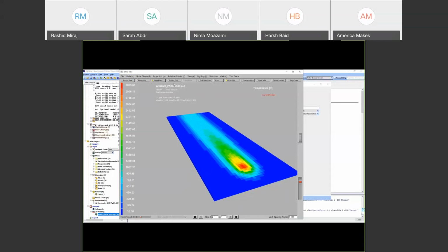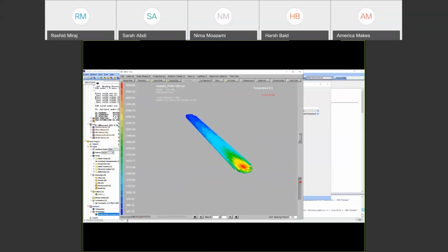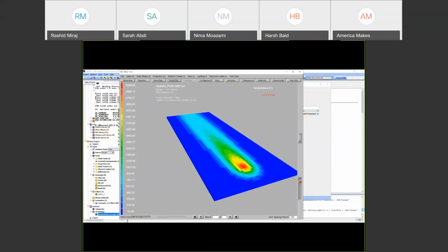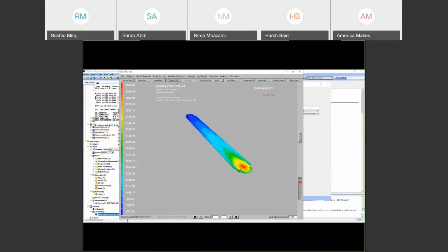And also, we have fused and unfused powder options. So you can click on the fused only, and then just hide the unfused powder surrounding, because this is laser powder bed fusion. And you can also hide the powder bed to visualize only what exactly the laser passed and has enough energy to melt the material.